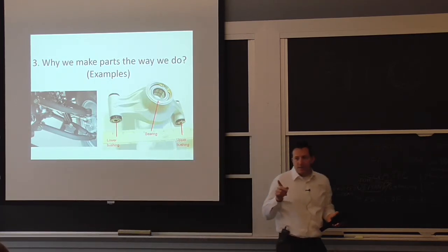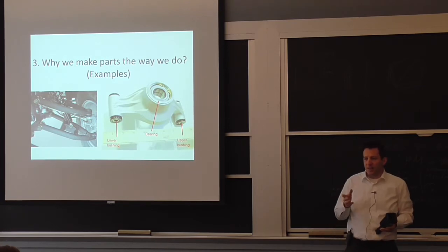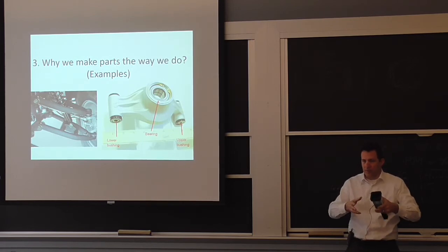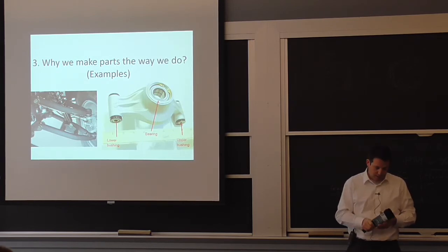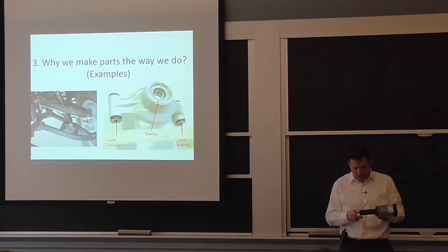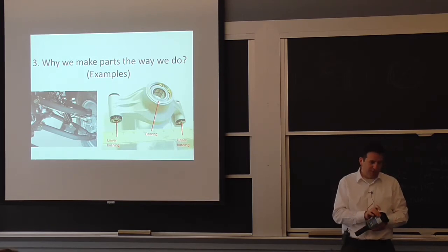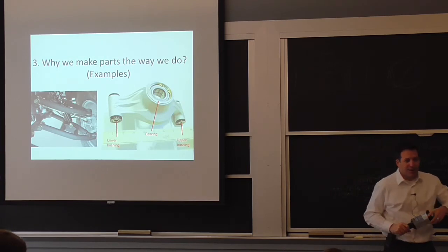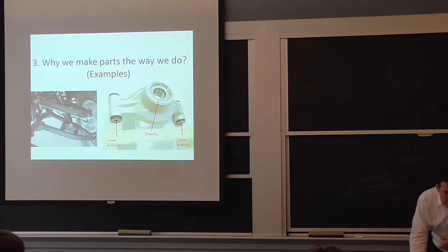They could make this for a similar price as making it out of steel, because with aluminum they use casting. If you were to go to steel, you bend things and do a little bit like this, just a hitch extension here. This one, they use two sections of four different kinds. This one is just a solid bar of steel. There's a little piece of tube put on, another piece of tube, and another piece of tube, all welded together. It's just a question of cost.